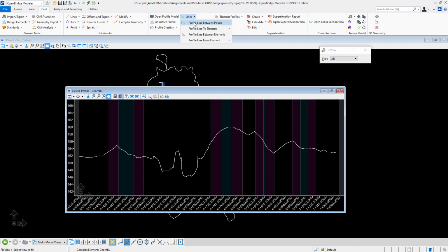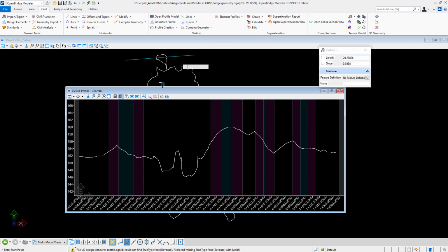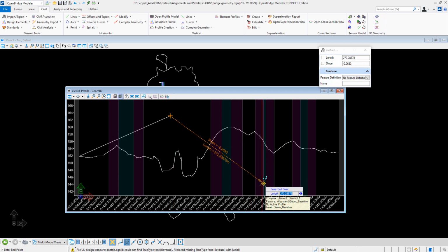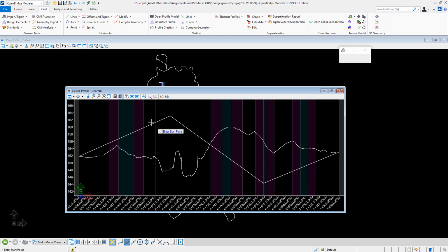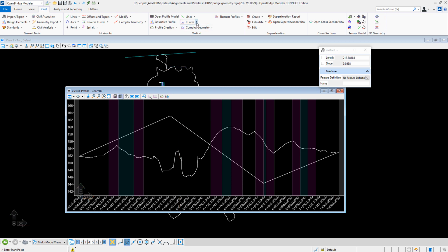So we'll just set up VPIs, or vertical points of inflection, where the profile should go. So it's all a graphical process. I said this should be closer to the terrain, as you can see, but just to illustrate the concept, I think it's better to do it this way. So I set up these VPIs that you can modify at any time. And now in between, I can set up, of course, vertical curves or parabolas.